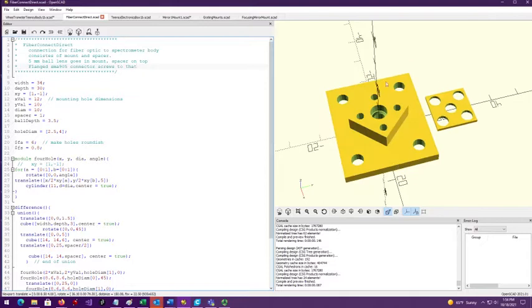Okay, so the fiber optic connector will require a lens. That lens drops down into this hole. It needs a spacer. This is the spacer over here. This goes right on top of this. Screws in using number 4 sheet metal screws.